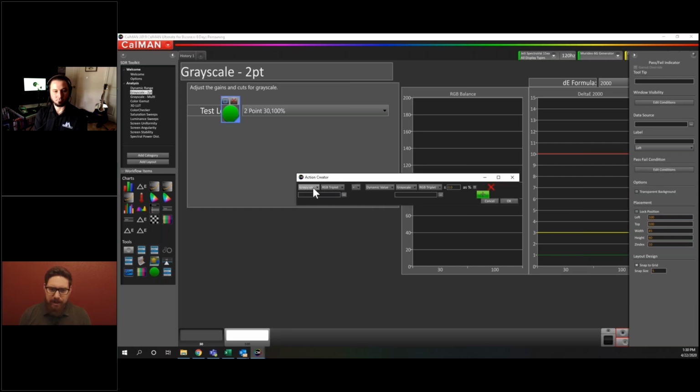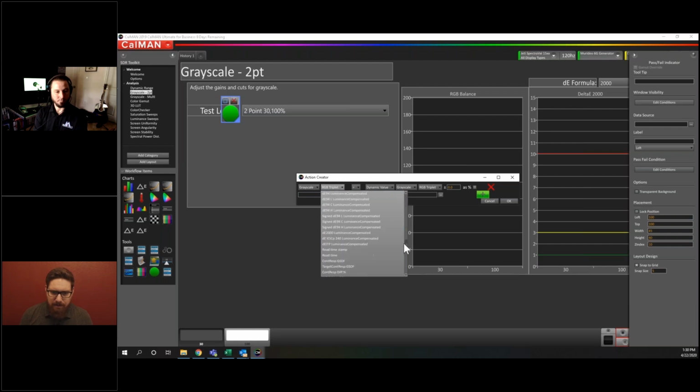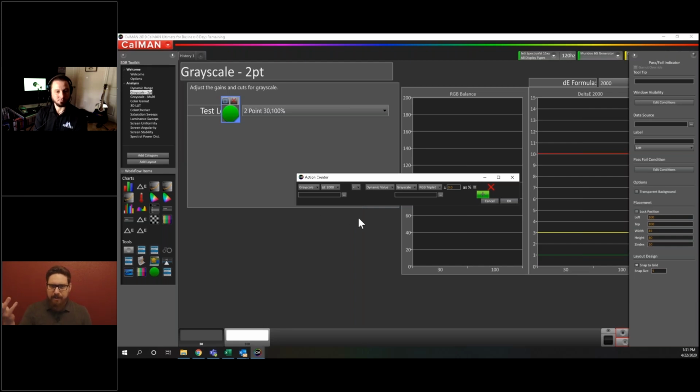So you could say, okay, grayscale, and I could say I want to have, sorry, I'm trying to find the Delta E2000 thing. Okay, I could have Delta E2000 over or under a certain threshold, and then it would flip that between pass or fail. So I could set thresholds in my workflow so that if my delta E's were under a certain point, then it would go green. If not, it would go red. And that would be an indicator that, hey, this isn't acceptable or this didn't pass our testing.